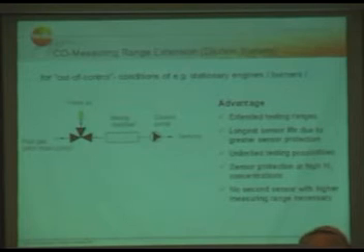And some manufacturers of analyzers don't provide this cross sensitivity compensation of H2, but we thought, okay, in many applications it's necessary, because especially at these gas engines where you have high H2, your CO reading will be completely wrong if we don't compensate for this. And this is done automatically within the sensor, and therefore you can also choose H2 reading in your display.